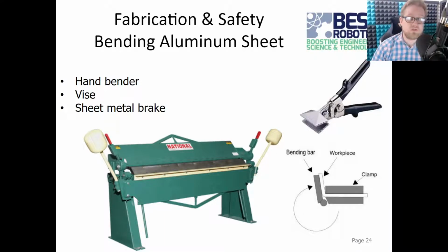Just be careful while you're doing it. If you do too sharp of a bend, you'll start to see some fracture lines on the edge, especially if you're doing a very tight bend. So you want to take your time with it. Don't hit it too hard. And try and do as shallow of a bend as you can get away with if you're bending it with a hammer. And try and get the radius of the curve larger if you can too. You can put a metal rod inside or even a dowel sometimes, and that can help give you that larger curve to make sure that you're not splitting or shearing it off as you try and bend it.